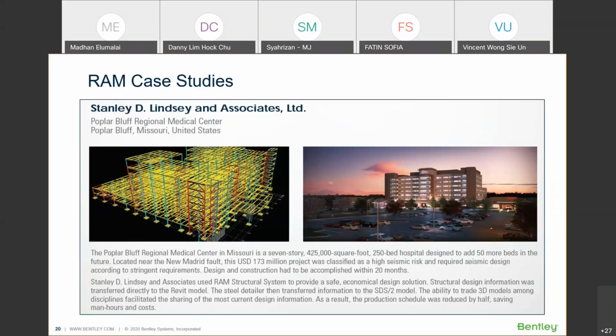That way, you achieve an overall performance gain, efficiency in the building, by distributing your lateral load only to important lateral frames, as well as your shear wall if it is a concrete building, rather than designing all your members, all your structural components, to take care of your lateral load. That way you lose your efficiency.